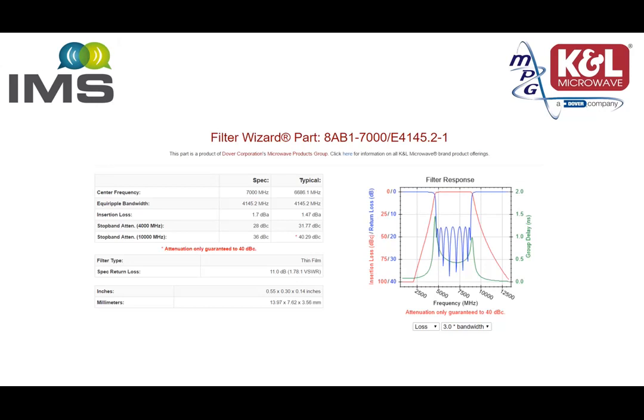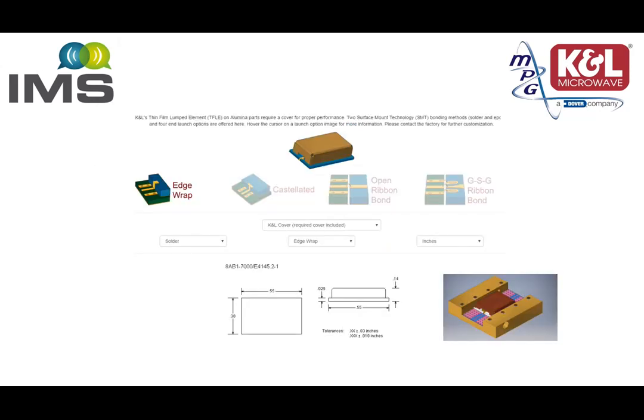You can switch and change the bandwidth of the sweep. You can also get phase deviation from linearity. Every point on the graph becomes the spec. So the performance shown to you is actually the spec for us. There is an estimated size in inches or millimeters. And if you hit enter, you get 4 options of installing the filter on your PC board.